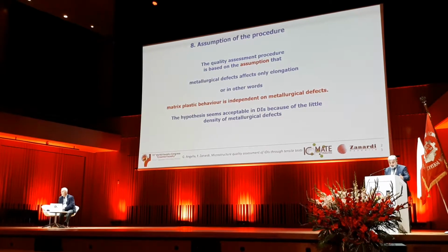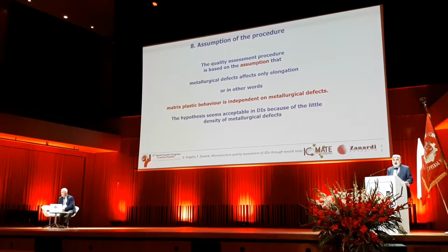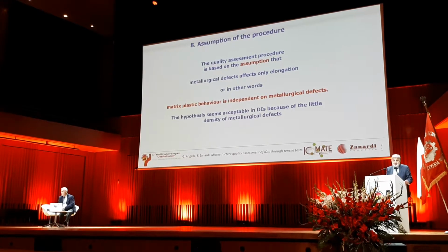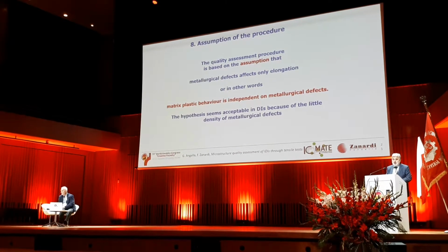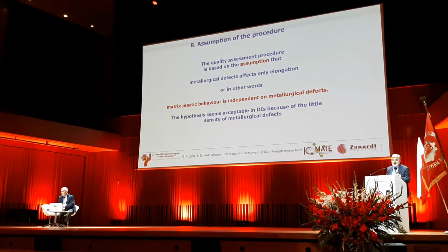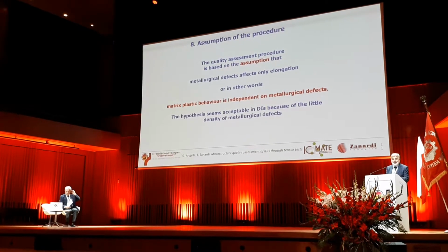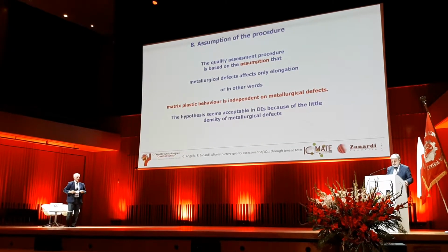Okay, so this is the assumption that we make, that with iron the defect density is not so diffuse, it is concentrated, which enables us to use fracture mechanics on one side and to use the separation principle between the matrix quality and the defect influence.